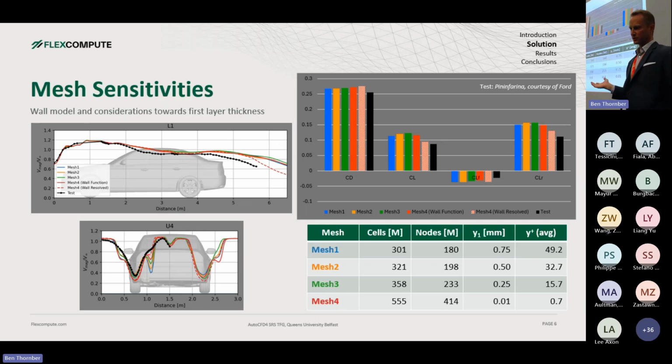One of the first steps we took with this is with the wall modeling approach that we have implemented. It's a little bit unique, so we took the opportunity to go through a study to evaluate what type of sensitivities we'd be seeing. So what we're looking at is using those custom meshes I was referencing, varying specifically the first layer height, and then balancing that with the number of layers grown to accommodate coverage of the boundary layer consistent with what the committee mesh was looking at.